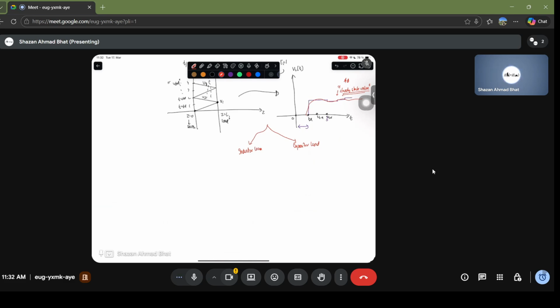because what happens is you are talking about the incoming waves, and then you are talking about the outgoing waves. You're talking about essentially the phase shift at this point. So how much is the phase shift and how that is occurring obviously depends upon the reflection coefficient of the load. And then coming back from the source, so this is the source and this is the load end, and then we talk about the source reflection coefficient as well.